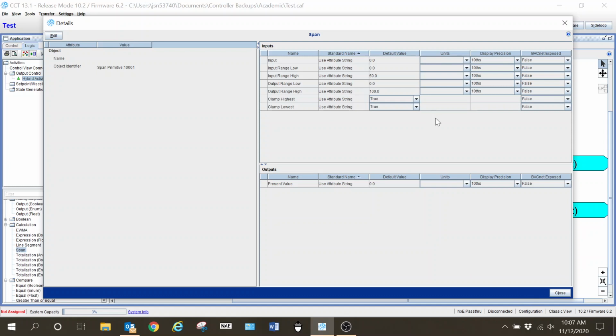You know, if this was a heat exchanger, again, a 1/3 valve, and when that PID loop told me that I needed to be at half of my total capacity, then the 1/3 valve should be at 100%, if those valves were equal.